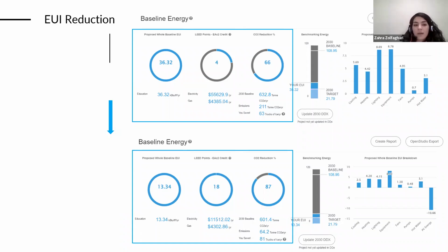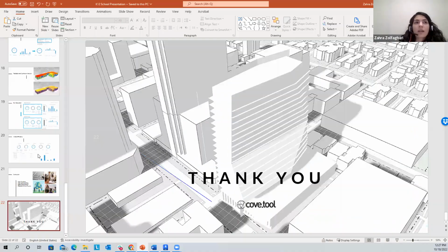We also calculated the operational carbon emission by multiplying the location-based carbon factors by energy consumption. So that's the way we calculate the operational carbon emission. In this case, you won't see a significant carbon emission reduction because of no energy change to the gas sources. Although the primary heating energy is electric, the primary energy for domestic hot water is gas, and we didn't really change any gas-related inputs on the baseline page. So although the EUI change is significant, you won't see a significant reduction in the actual emission of your project.